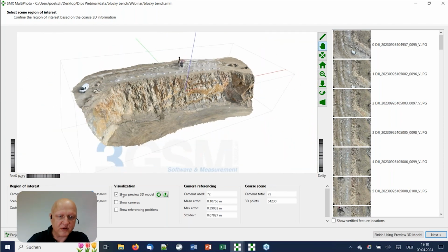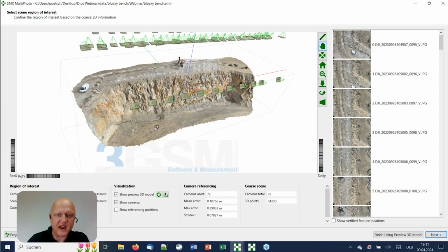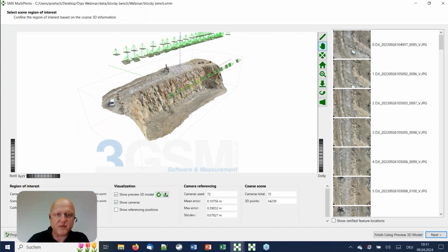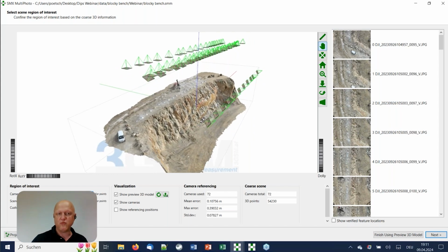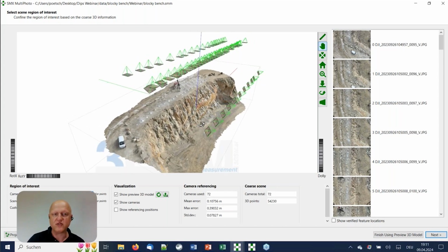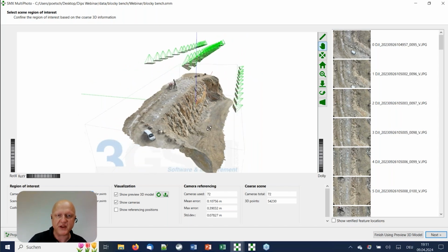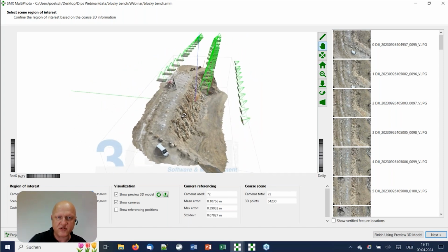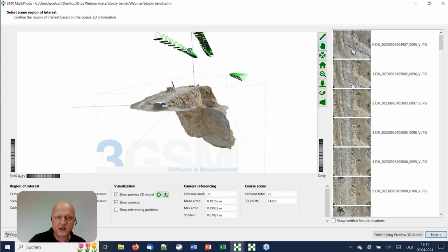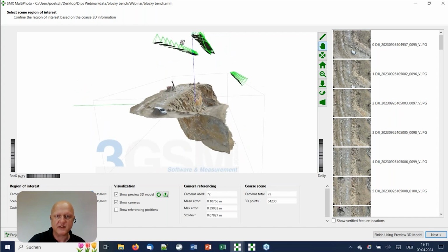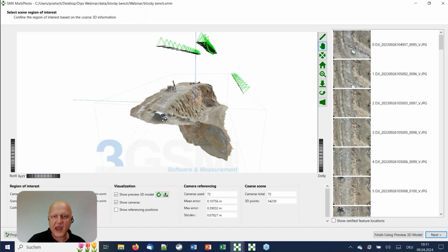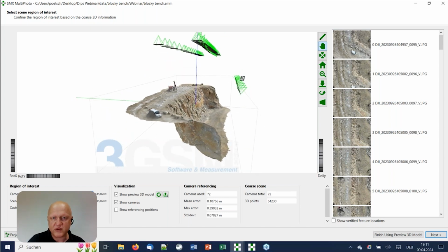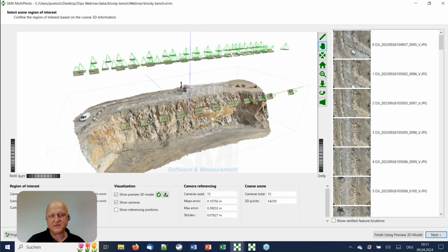And what I want to show here is also the set of cameras. You see these green pyramids. These cameras are the positions at the time when the drone took the photo, reconstructed from the pictures. And we see here one track looking vertically downwards, this one here. And there is another one overlapping here. And we see here on the right-hand side, the frontal photos towards the face.